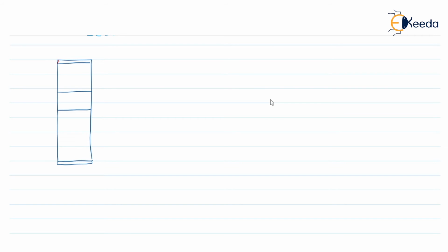So on this metal contact there will be the emitter terminal, and on this metal contact there will be the collector terminal. So this region is P plus plus, this is N plus, and this is P, and on the N plus region there is a metal contact. So this is the base region.